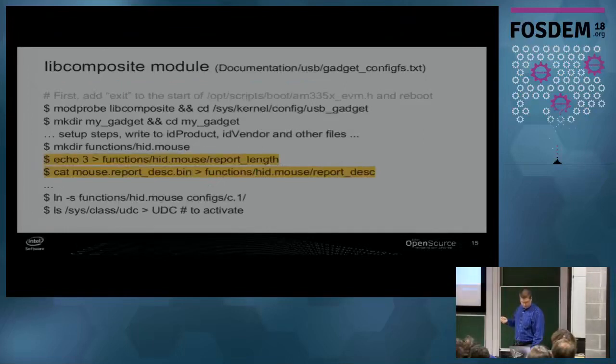So for controlling, of course, as this is going to be about the open source utilities, and we already have a great USB gadget stack in the Linux kernel, you basically don't need anything else. From the BeagleBone Black, you will be plugging the USB gadget cable to the host device, and that's it. You will be able to have your mouse, keyboard, serial port, and any mass storage gadget there. So basically that will fulfill most of the needs when you already have the display with the HDMI encoder.